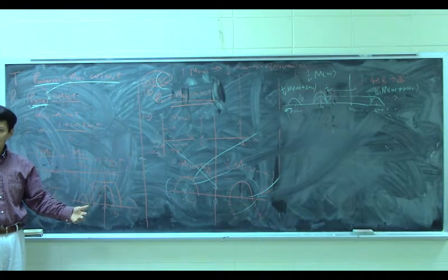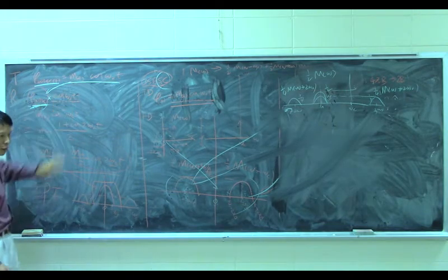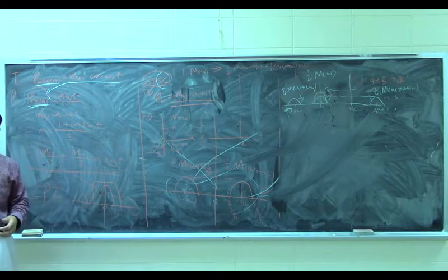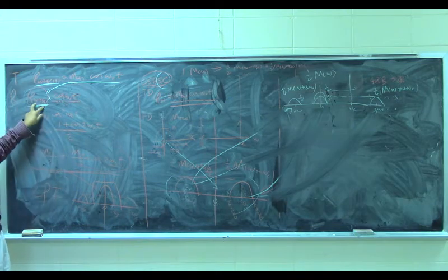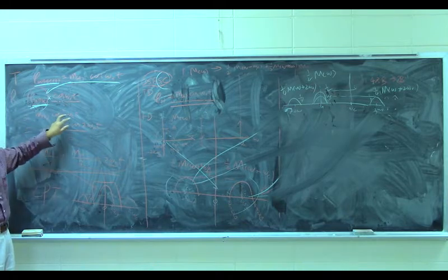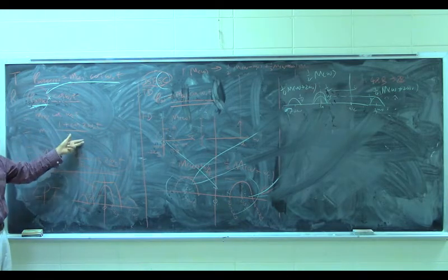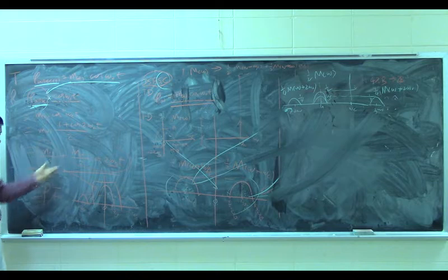You may ask, why do you multiply this, use a low pass filter, and get what you want? How do I know that is correct? Alright, a mathematical proof. You receive this signal, you multiply by this cosine, actually you have m(t) times the cosine squared, which equals this. All these are trigonometry, right? So it equals this.